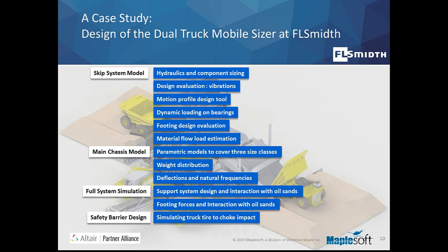We have created a tool for motion profile design, similar to what you have seen in that simple pick-and-place robot. It is very important, for this heavy machine that goes up and down, that you design a speed profile that provides the correct timing and also does not have high acceleration. With the system that we have, we were able to calculate dynamic loading on various footings, joints and bearings. The footings were also part of this model.